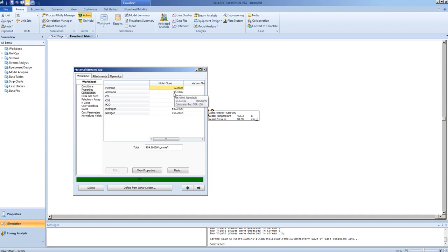There was a lot of ammonia produced, and any carbon dioxide, carbon monoxide, and some of the water have been utilized. We can also see that the hydrogen and nitrogen have decreased. What has actually happened is that you have had some methanation happening with these 3 components, where methane is formed from these 3 components, and you have had ammonia conversion happening.